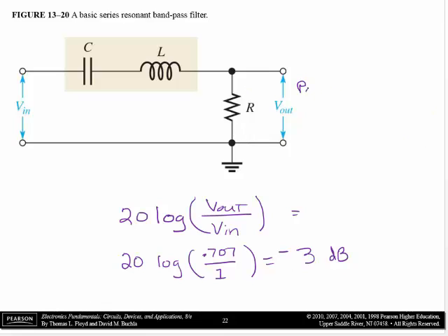If I calculated power out, and you can calculate power out because it's I squared R, or because it's V squared over R, whichever way you calculate it, and you can calculate your power in. And if at some frequency the output power is halfway down, I would say 10 log of 1/2 over 1, because input power was 1, output power is down by 1/2.